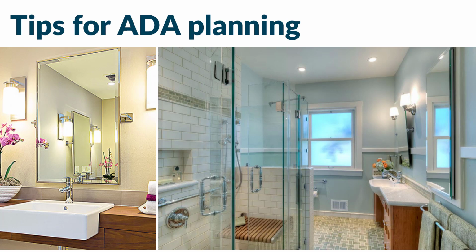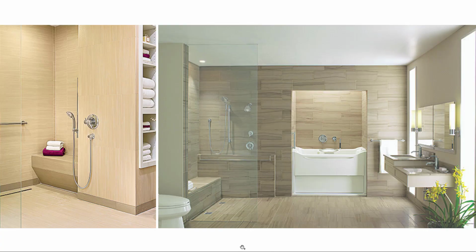So here's a couple more inspirational images, looking into this idea of a large open bathroom with a built-in shower seat and what these spaces might actually look like rather than just being in a plan view. Looking here, the whole idea of a barrier-free bathroom situation can be really nice and super open. And here, we're seeing the whole shower that you could just walk or roll into with no barrier. It's slightly angled to keep the water this way, but it's all totally open into the space. So there's no hazard, no barrier here or here for the individual using it.